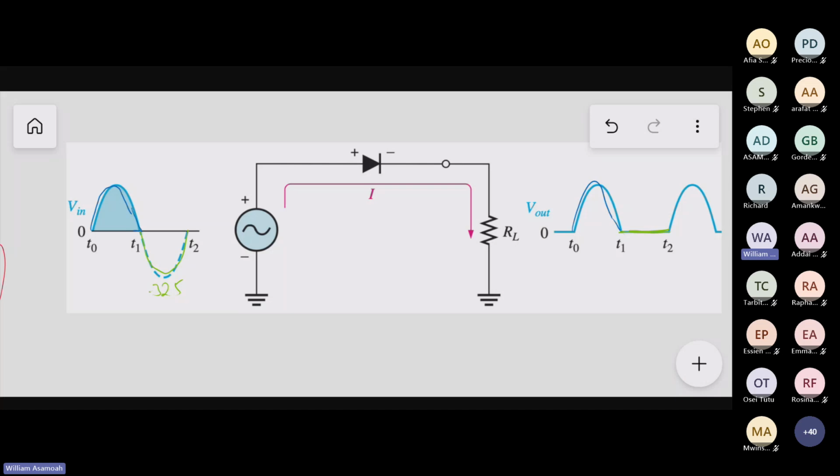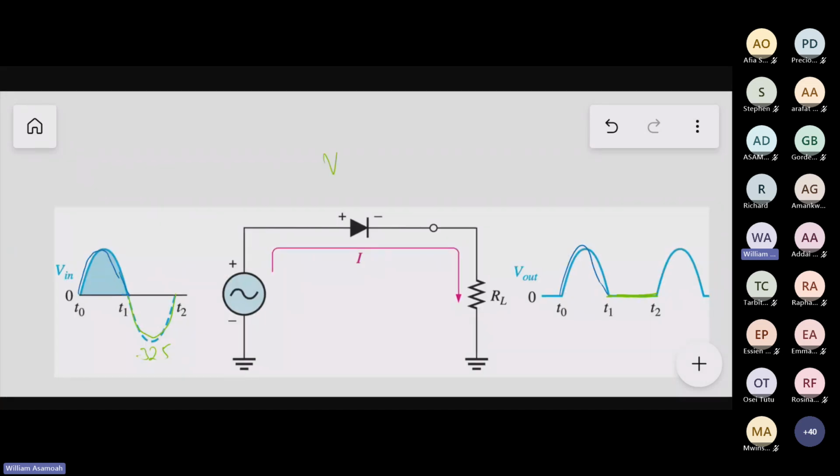When you are building a rectifier circuit and it's going to be a half wave, you need to select the diode so that the diode can withstand a maximum reverse, or it can have a VBR greater than, not greater than or equal to, it should be greater than 325 volts. Because if the maximum breakdown reverse is lesser than this, the diode will not function. It will spoil. It will not be able to really rectify.